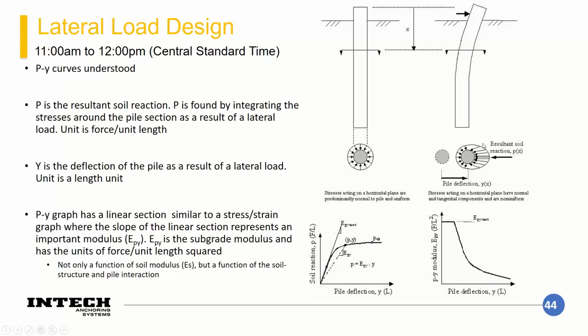So it's in part due to the geometry of your pile, just as much as it is the actual soil strength around it. And the deflection is obviously much easier to visualize. It's just a measure of how much it moved with a certain load. That's basically, in a nutshell, what the PY curves are. Without belaboring it too much, I'm happy to talk about it offline if someone wants a deeper understanding of how this works.